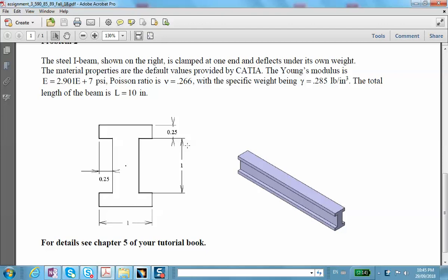When I do it initially right now, I'm not going to use any planes of symmetry, but then quickly I'm going to come and redo this thing with taking a plane of symmetry which is along the length of the beam. Now keep in mind that because this is sagging under its own weight downward, there's only one plane of symmetry. There are no other planes of symmetry.